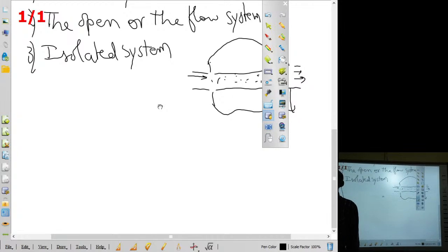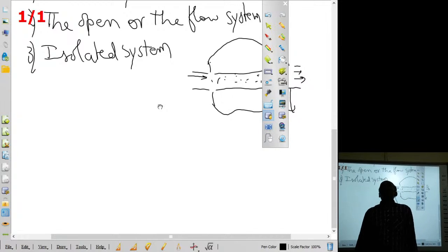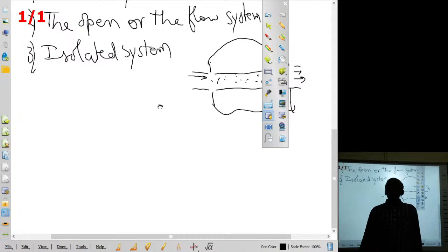Well, if you see the thermodynamic books or thermal engineering books, what you will find is that the example for an isolated system is a bomb calorimeter. Because there is some fuel inside the calorimeter, by passing electric current we ignite the fuel, it burns, and there is water in that bomb calorimeter, the temperature of that water will increase. But it is fully sealed, nothing will come out. So here, energy in the form of fuel is now going to water. That is also inside.